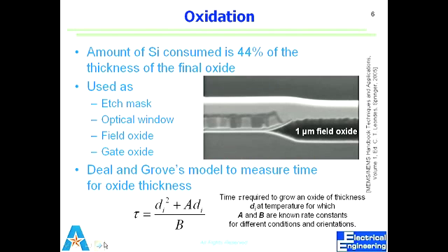I do my BHF and transfer that pattern in silicon dioxide, right? And I can do further processing, but before that, I'll get rid of the resist because I don't need it. I'm getting rid of it because the resist can come off and become lodged, those particles somewhere, and change the etching condition here.